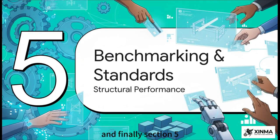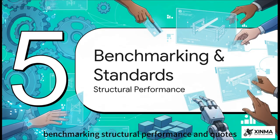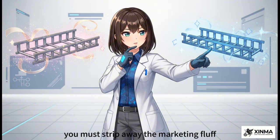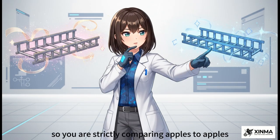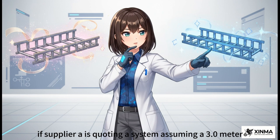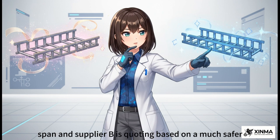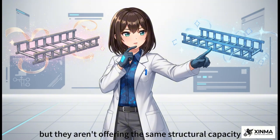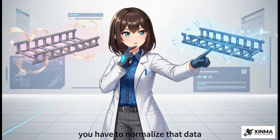And finally, Section 5, Benchmarking Structural Performance in Quotes. This is such a crucial point when you're in the procurement phase. When reviewing bids, you must strip away the marketing fluff. You absolutely have to normalize competing supplier quotes so you are strictly comparing apples to apples structural performance. Think about it. If supplier A is quoting a system assuming a 3.0 meter span, and supplier B is quoting based on a much safer 1.5 meter span, their prices will look wildly different, but they aren't offering the same structural capacity. You have to normalize that data to ensure the engineering integrity is identical before you even glance at the price tag.